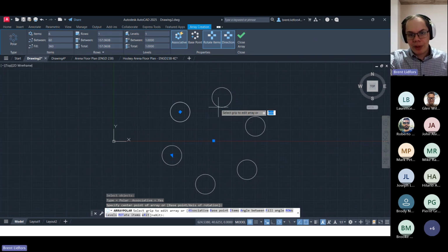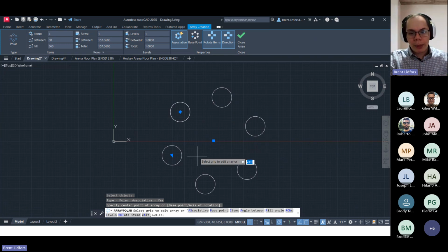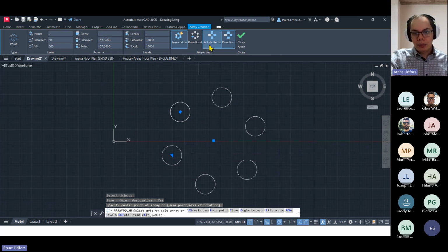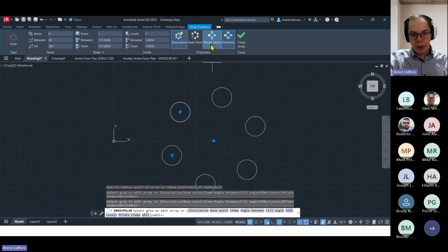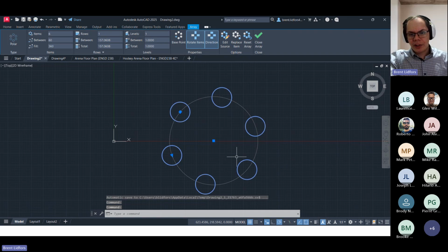It doesn't really matter which way these are rotated, because each of these circles looks the same anyway, no matter how I rotate it. So most commonly, you're polar arraying circles out. But if you're arraying out some other shape, like the triangles that we showed, you might have to determine whether it's rotated or not. Most often, they're bolt holes or screw holes set in a circular pattern, so they're not often some other shape.